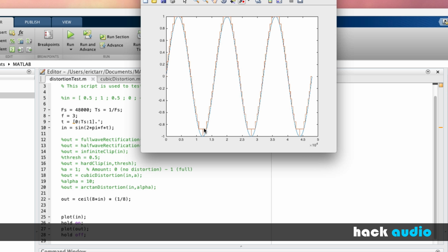So now we actually have 16 possible amplitude levels. So we have to keep all these different things straight: the number of amplitude levels, what kind of scaling we need to do to our input signal to achieve those levels, and think about, well, what's the equivalent then in terms of the number of bits? When it comes to bit reduction processing, a lot of times we want to be able to say, we'd like to have 2 bits. We'd like to have 4 bits, 8 bits, 16 bits, and make sure that our output signal has the appropriate number of levels.